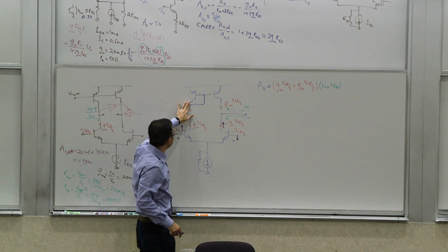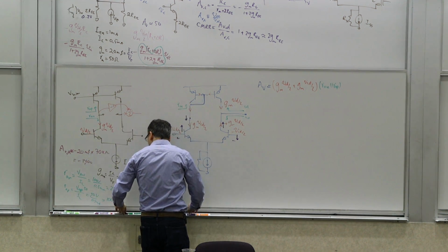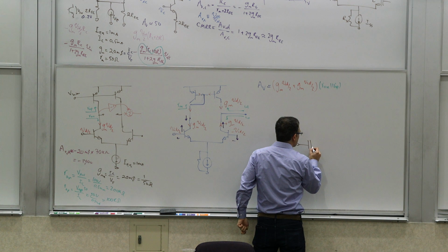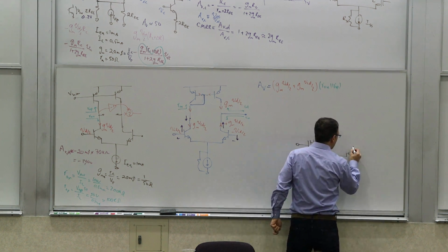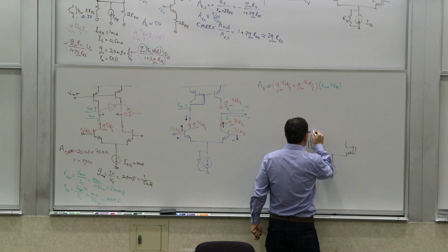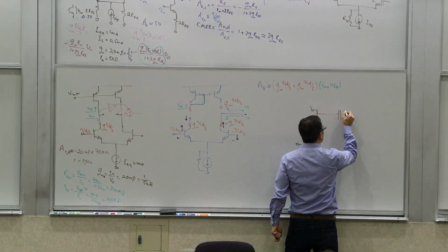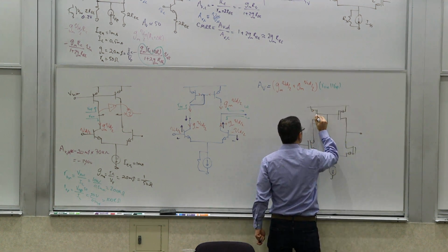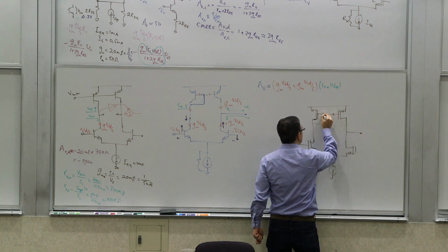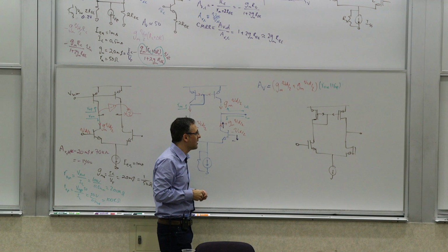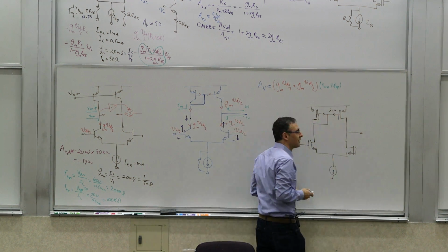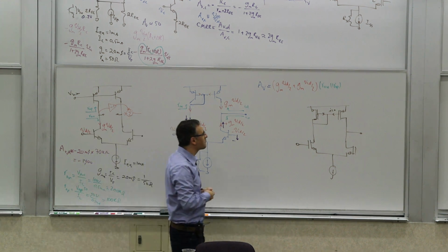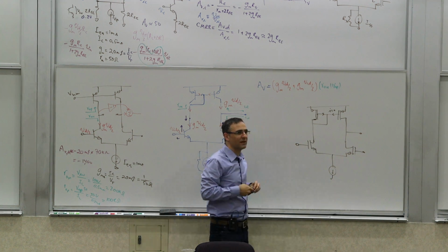So this stage is actually a pretty important stage. And again, you have a MOSFET version of that too, like everything else. So for MOSFET, it would look like this, but the analysis is exactly the same. There's an actual advantage to the MOSFET from one perspective, which is that you don't have to worry about these base currents. You still need to provide this pathway, otherwise that node will be floating, but these currents are zero. Here, you're drawing some of this base current through here, so you have to worry about that. But other than that, this is a very classic differential to single-ended converter.